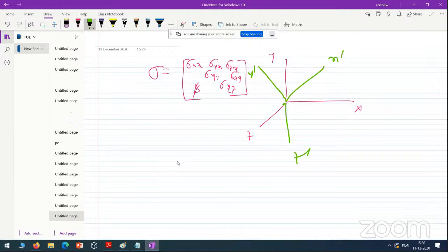The first invariant, the first information which is preserved, is the trace of this matrix. If you represent the stress with respect to different coordinate systems, for every representation sigma xx plus sigma yy plus sigma zz remains the same. For instance, if you write this with respect to the principal axes, the matrix is sigma 1 0 0, 0 sigma 2 0, and 0 0 sigma 3.